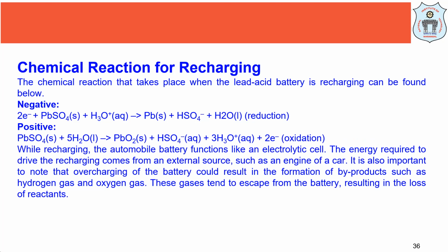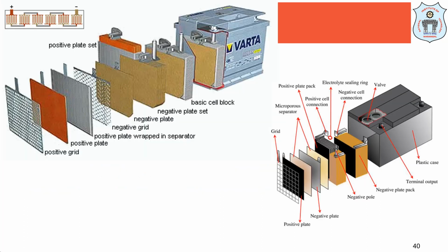A typical sealed lead acid battery will consist of 6 cells mounted side by side in a single case, and these cells are coupled together, each having 2 volts. It adds up to an overall 12 volt capacity of the battery. So even though this battery is heavy, these lead acid batteries are still preferred over other lightweight options because they are able to deliver large surges of electricity, which is required to start a cold engine in an automobile.